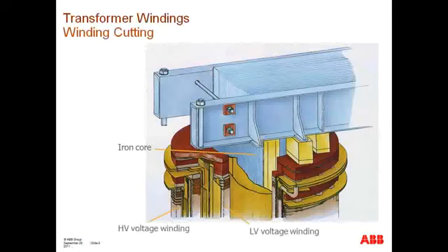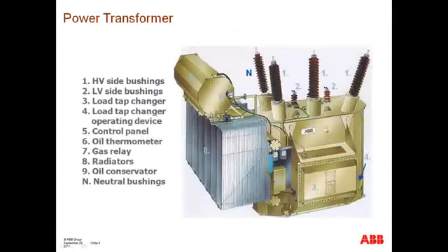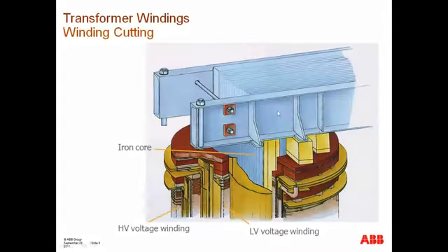Now, this is a view of the core inside of the transformer, or what's actually inside this metal enclosure. And what you're going to find is the following. You have a metal structure, okay, with several layers. This is the core, and the core is laminated to reduce or minimize the amount of eddy currents, the amount of losses, from a transformer design perspective. Okay, and then you could have multiple legs inside the core.